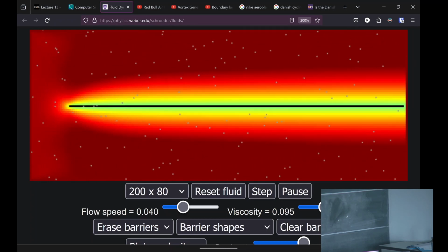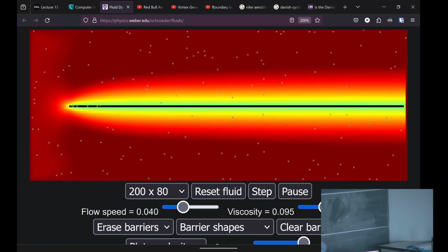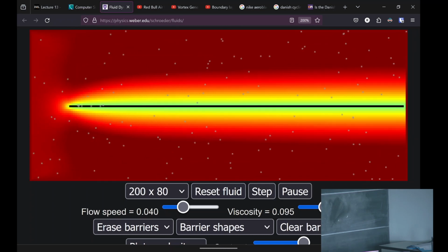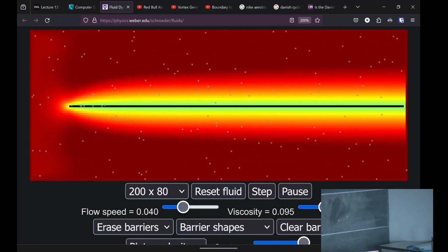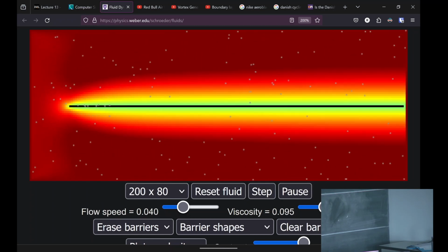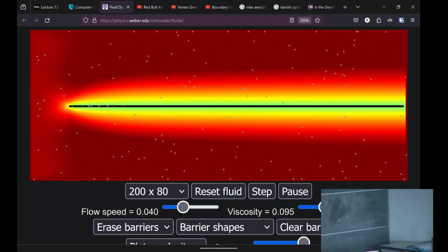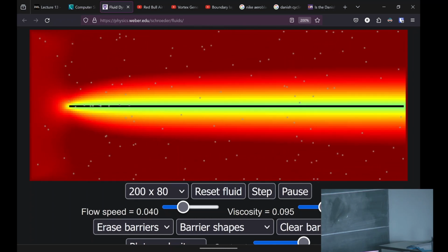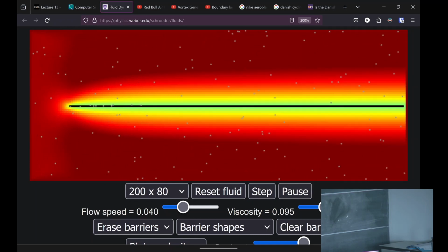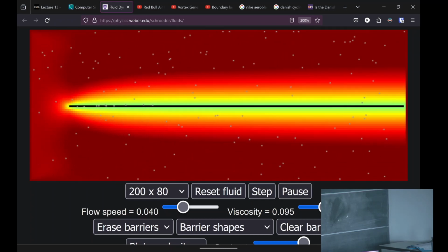Yes, please. On this, is there a way to represent the transition period for the boundary layer? Because I'm still not entirely sure what the transition region is supposed to be. So the transition region is a region where we don't have a fully turbulent boundary layer yet, and we don't have a laminar boundary layer. This is actually a laminar boundary layer, so it's very smooth. The transition region is when there might be a fluctuation that happens, but then it's dissipated, and then another fluctuation dissipated. Whereas in the turbulent one, the fluctuations are just continuously happening. So don't worry too much about the transitional one. This is a laminar one. Turbulent flow is much more expensive to solve numerically than laminar flow. So this is basically a laminar solver, but it can still show us the boundary layer.